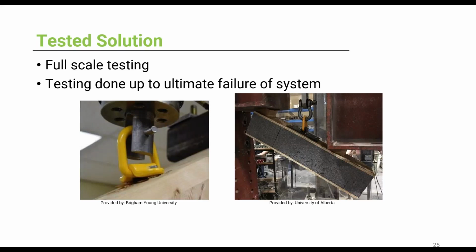Full-scale testing was done on all the yoke anchors with universities in the US and Canada. All the testing was done up to the ultimate failure of the system using different timber elements. On-site conditions like anchor placement were simulated as much as we could. The results from all of this testing were used as a basis for the values in the design guide, which we'll see later.